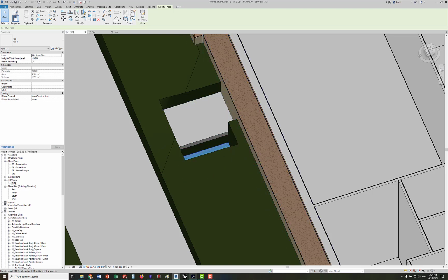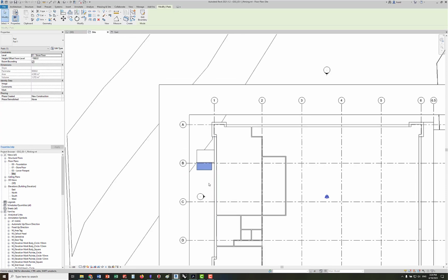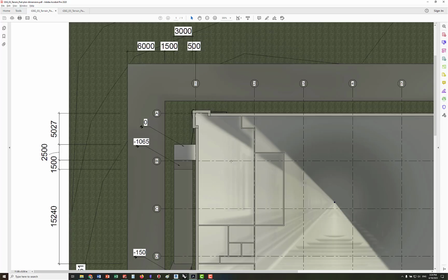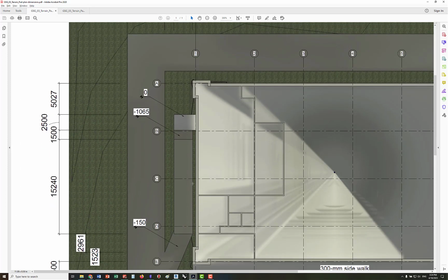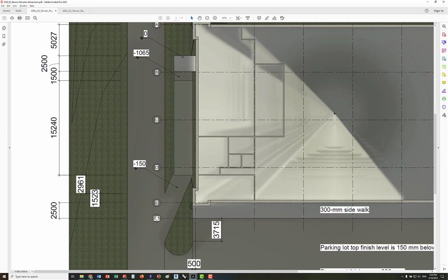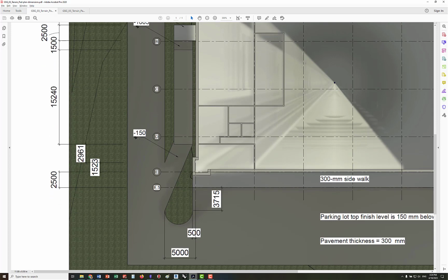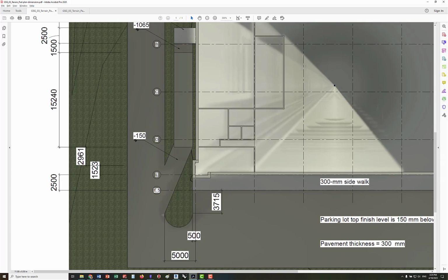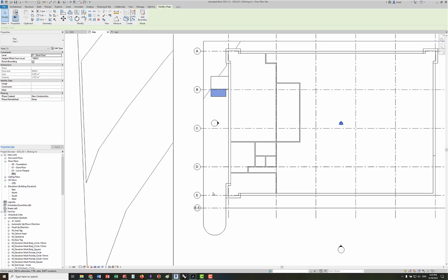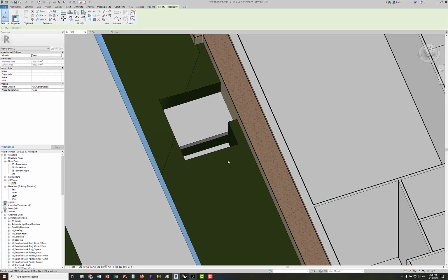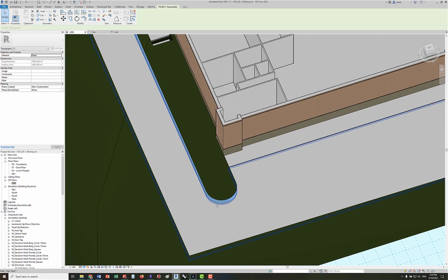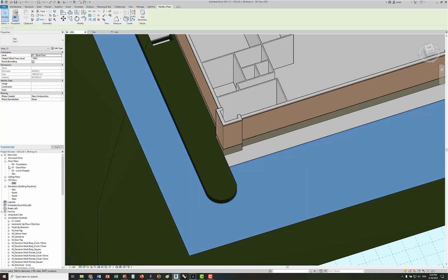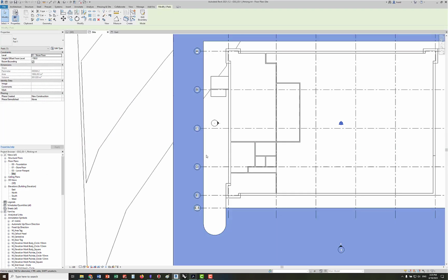So now I'm almost done. I need to connect this part to the entry somewhere here, which is this kind of driveway, but it's driving, and if you're going from the parking lot elevation negative 150 and then dropping all the way to negative 1065. So let's create that entry here. So I need to select that pad, which probably it's hard to pick on just the side plan. I will go into the 3D, here you go, pad, and then going to the side and then edit.